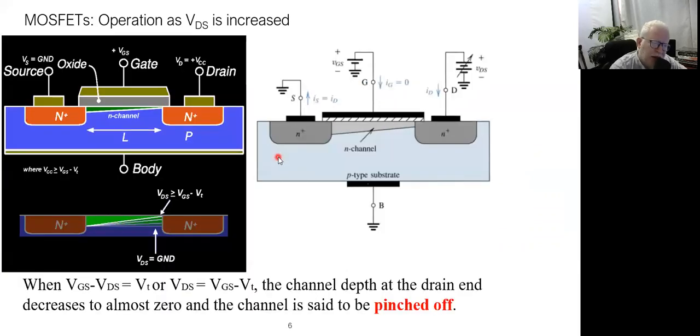However, we have studied together that at a certain voltage, which we call the saturation voltage, a phenomenon called pinch-off starts to appear. This phenomenon is simply observed here, where the width of the channel tends to be 0, and this is what we call the saturation region.